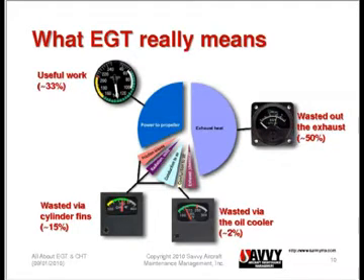Another small portion of that energy winds up being wasted heating up the oil. And our aircraft engines deal with that heat by passing the oil through a little radiator called an oil cooler and dissipating that heat into the air as well. So basically 2/3 of the energy in our fuel winds up heating up the air and not propelling the airplane.